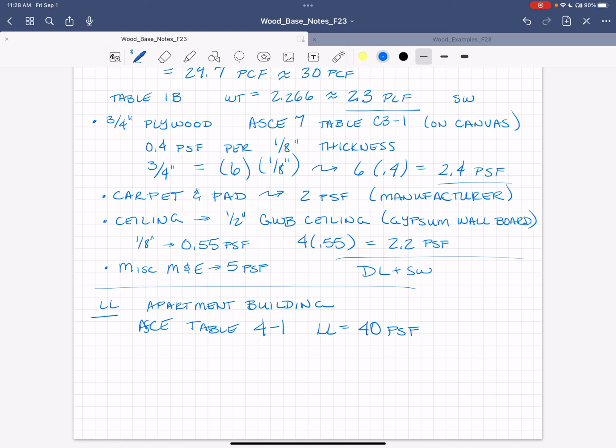So the live load per joist is going to be the 40 pounds per square foot times 1.33 feet. I'll let you think about where that came from. How much is 1 1/3 feet? So think about 16 inches. That's where my 1 1/3 feet is coming from. 16 inches on center equals 1.33 feet.